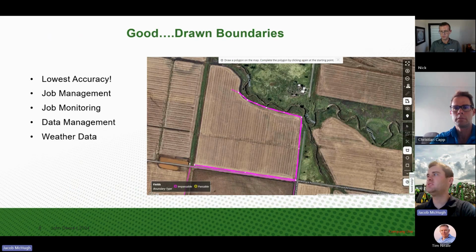This map isn't geo-referenced, and you can see obviously this one isn't the best drawing that you'll see out there, but effectively anytime you're dropping one of those data points in the corner of a field, no matter how far you zoom in and how accurate you try to be in terms of placing those data points, you're still only going to be meter accuracy, because those Google Maps that we use there, those background maps, they're not geo-referenced. You think you're dropping a data point on a fence post, but you might not be when it comes to actually utilizing that boundary in the field.